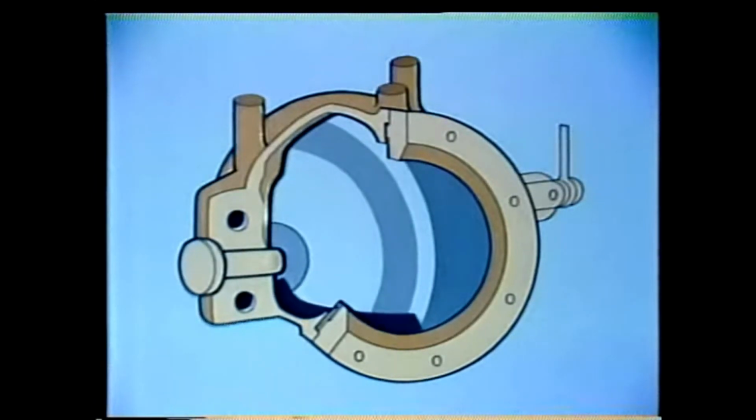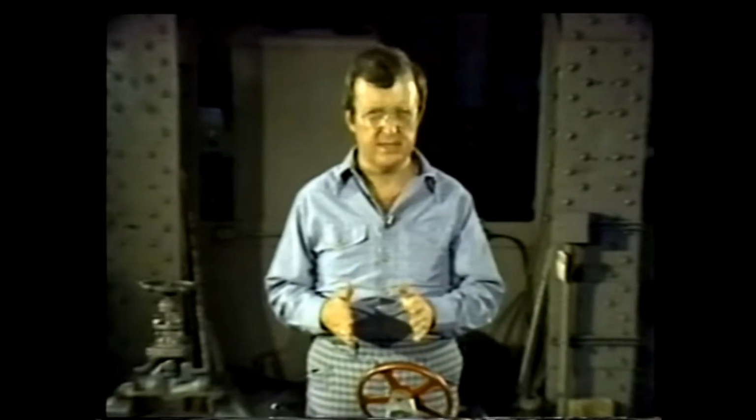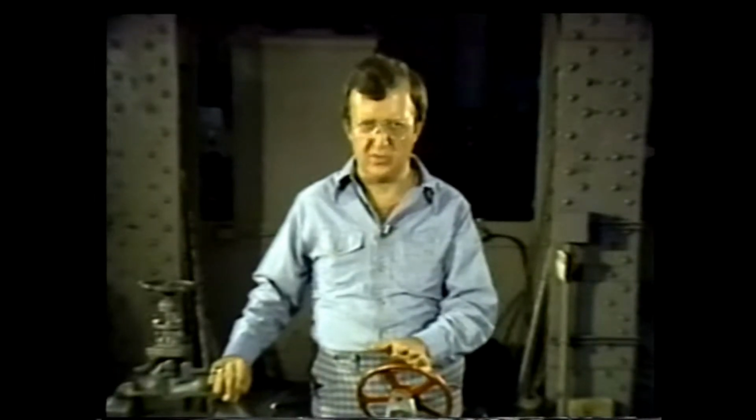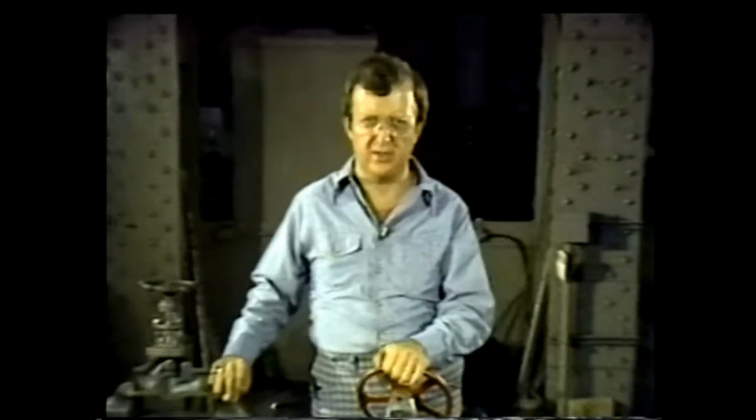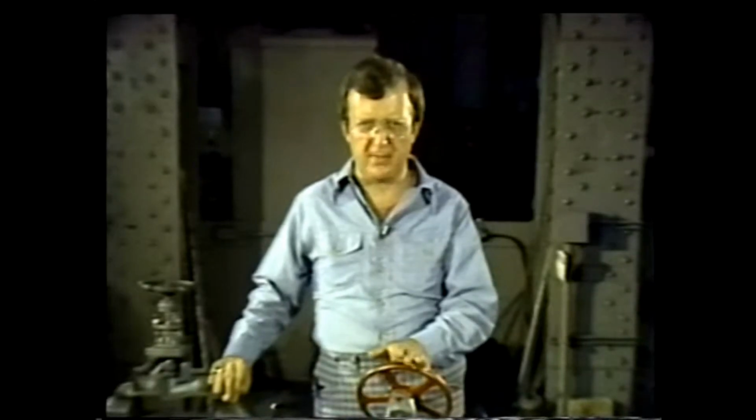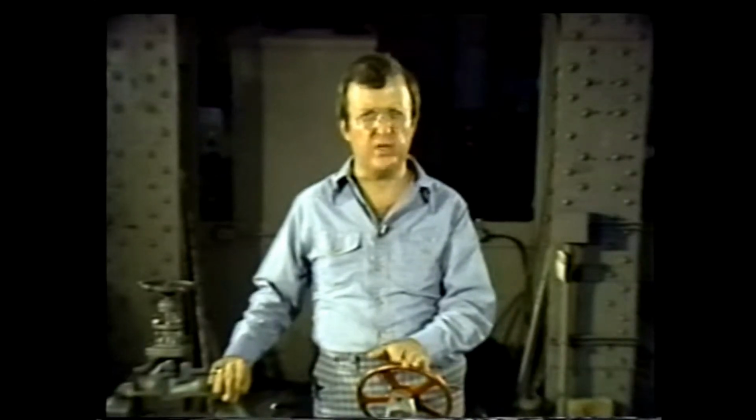It also is resistant to clogging, which makes it adaptable to a wide variety of flow materials. For example, slurries such as pulp, coal, or ash can be controlled through the V-ball valve. Control is applied by a wedge shearing action. As the ball is rotated to close, any material that might clog the passage is sheared off.